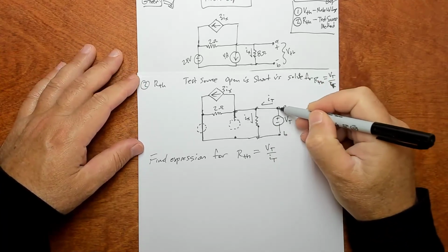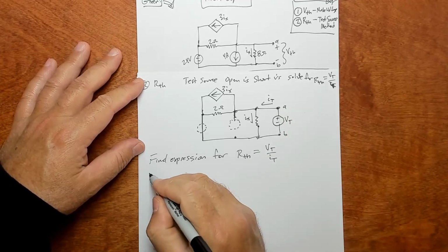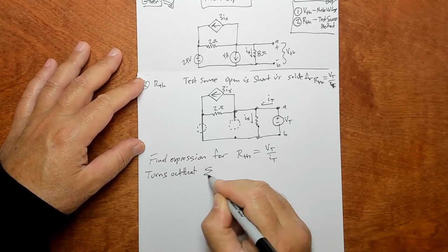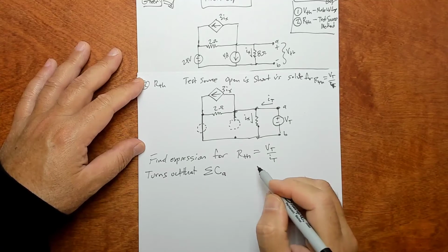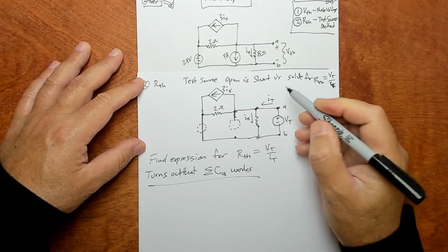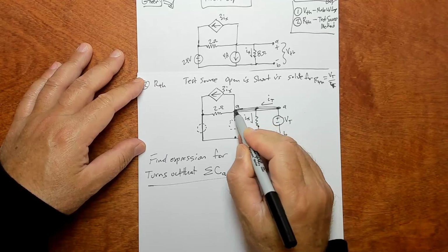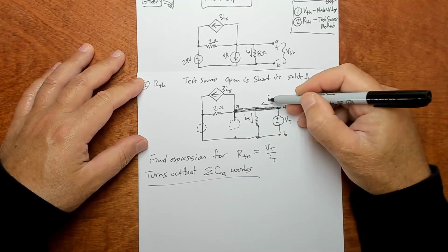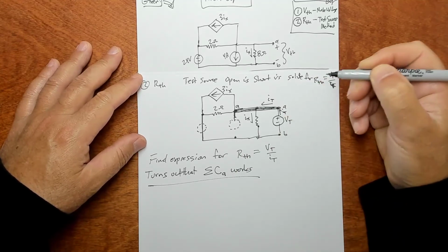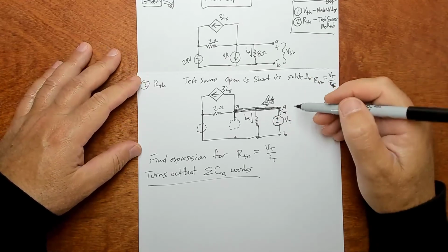And so you look, and it turns out that the sum of the currents at node A works. So this is node A. This is also node A. All across the top is node A, because there are no devices in there. And I've drawn I sub t kind of going through node A. Really, you could scoot it down here if you want. This is I sub t. If it's confusing, draw it coming into the node.